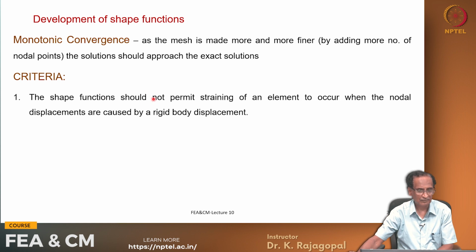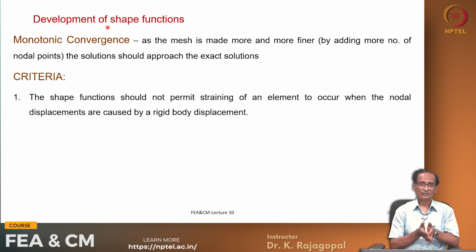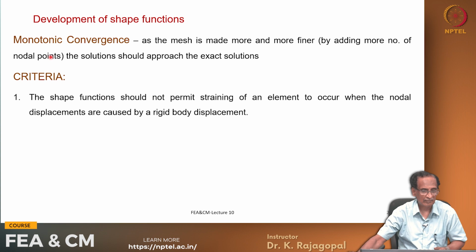The next step is we need to develop our shape functions. The shape function is the major component that we need to develop, because our shape function matrix is dependent on the shape functions, and then our B matrix is also dependent on the shape functions that we have, N1, N2, N3 and so on. And